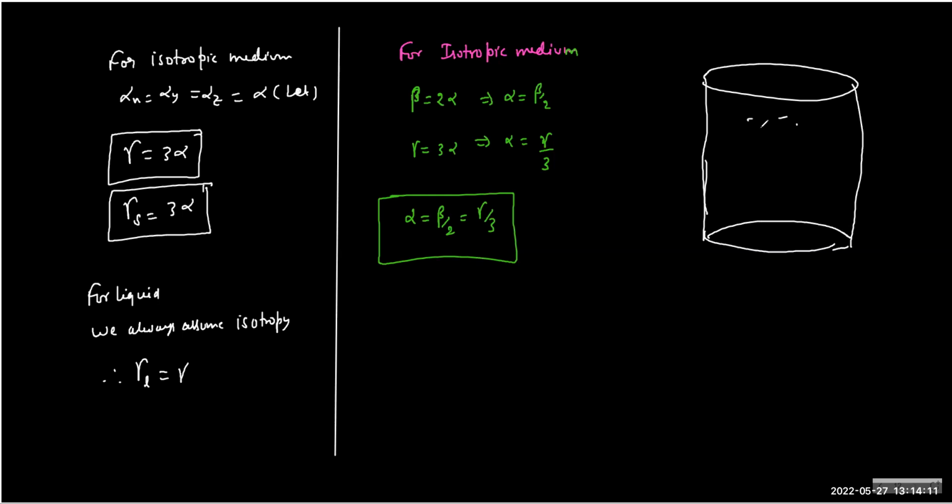If I consider this volume, then I must apply the volumetric expansion because this area will expand and this length will expand, and so the volume will expand. And because it's made of the same material, the shape will be undisturbed. So things will grow in proportion, and therefore you can apply the volumetric expansion.